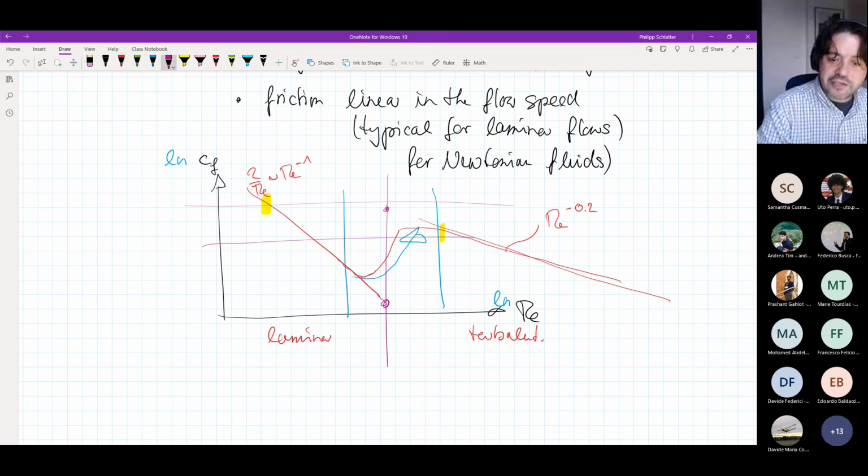But I think it's actually very good how you answered, because it's not fully clear what is larger and what is lower. It really depends. I would have needed to specify, for the same flow rate, whether laminar or turbulent flow has a lower CF. But of course, that's also a strange question, because you cannot just choose whether you're laminar or turbulent. Or, I mean, sometimes you can with flow control, for instance, but not always.